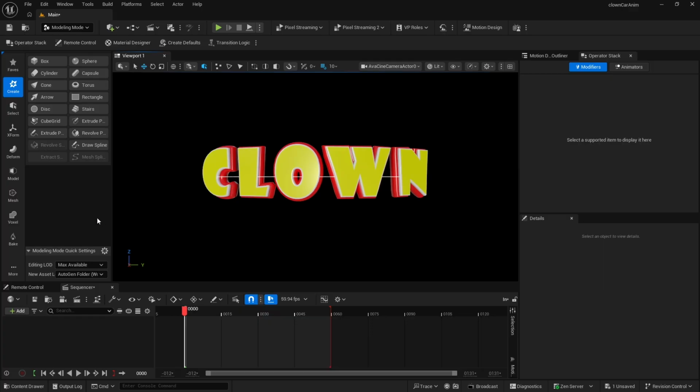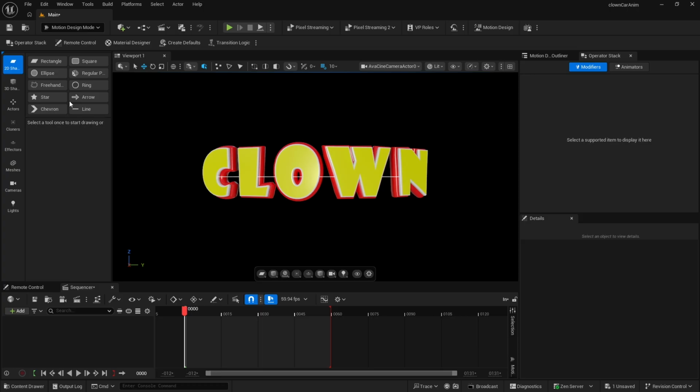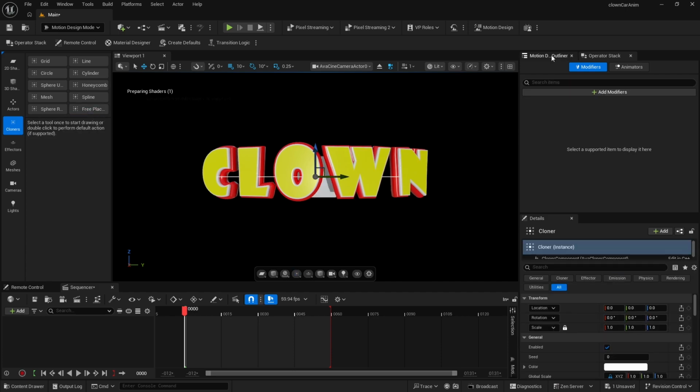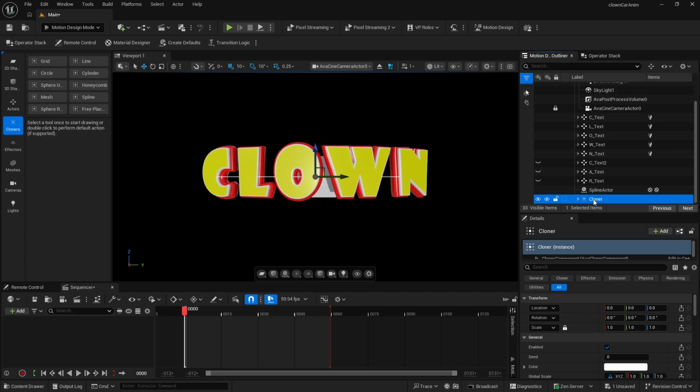Now to animate these, we're going to need to put them in a cloner. I'm going to go back over here and go to my motion design mode right there, and we'll go to cloners. And like I said, we're going to use this free place cloner. So I'm going to double click on it. That is now in our outliner right here.